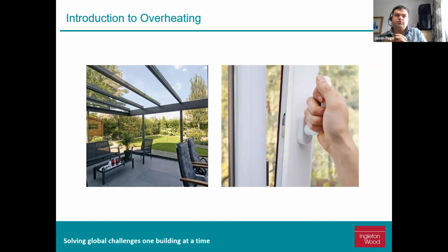I'm not going to go too deep into the science of that, but essentially infrared radiation comes through the glass, loses some of its energy and the wavelength shortens. Once this happens, it can't get back through the glass, trapping it in the room. So the trick to reducing the energy getting in is not to let it in the first place, whether that's by using external shading, shutters, smaller windows, etc.